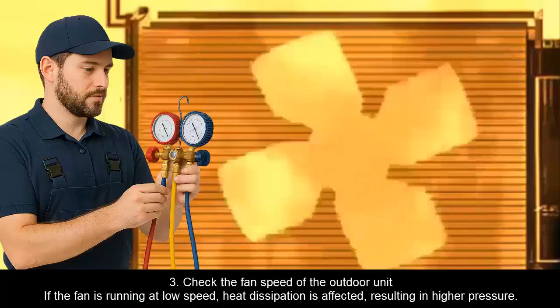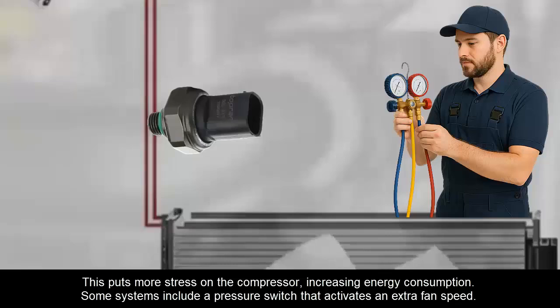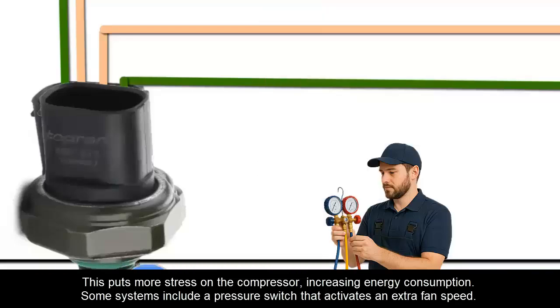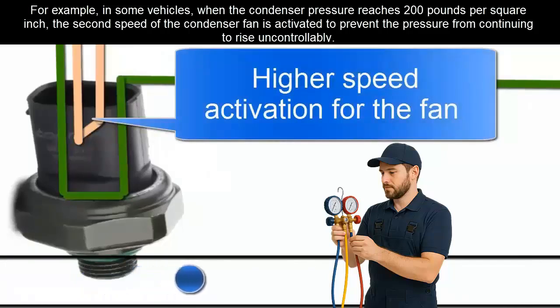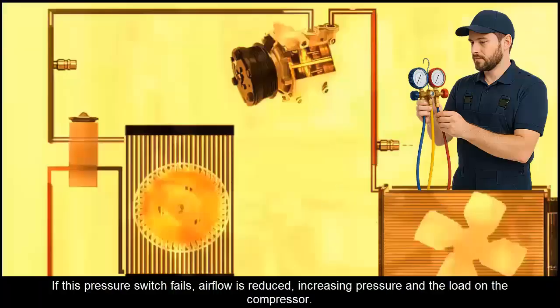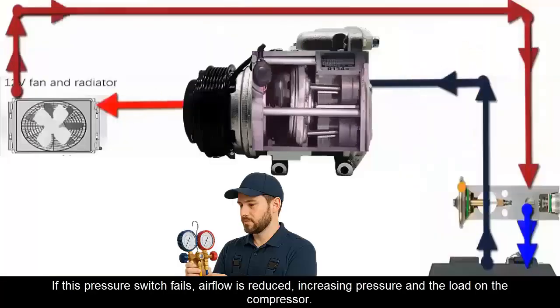3. Check the fan speed of the outdoor unit. If the fan is running at low speed, heat dissipation is affected, resulting in higher pressure. This puts more stress on the compressor, increasing energy consumption. Some systems include a pressure switch that activates at extra fan speed. For example, in some vehicles, when the condenser pressure reaches 200 pounds per square inch, the second speed of the condenser fan is activated to prevent the pressure from continuing to rise uncontrollably. If this pressure switch fails, airflow is reduced, increasing pressure and the load on the compressor.